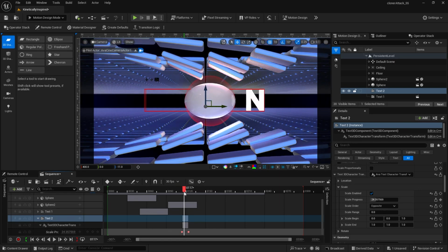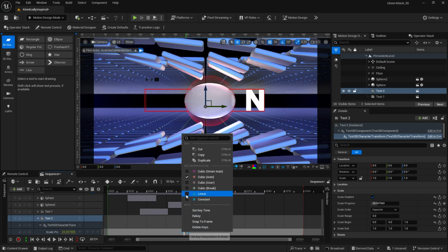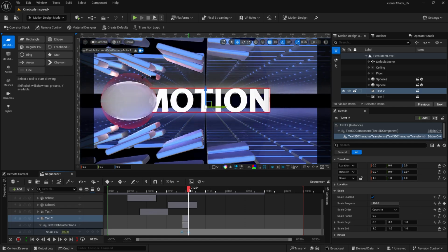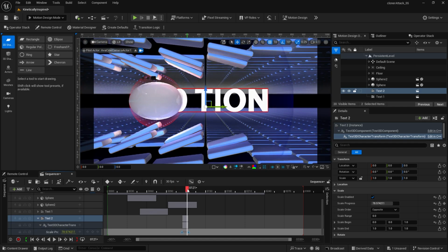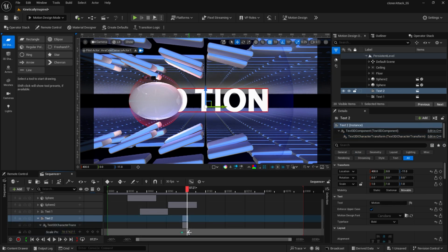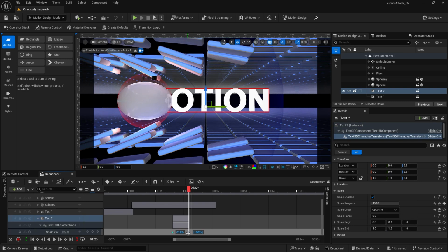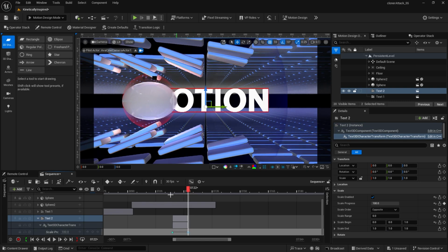All right, so it looks a little slow at the beginning, so we'll need to make some adjustments there. First of all, I am going to go ahead and set this to linear. That might be why. It's easing in, and we just want it to be a constant velocity. So that looks a little bit better. I think that was our problem there, and so maybe a little slow. So we'll make sure that we're not on both of the keyframes. And again, I'm going to use the plus button to zoom in just a little bit on this. And I'm going to drag that back just a little bit, maybe 2 frames to see what that does.